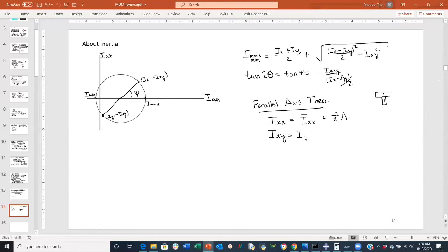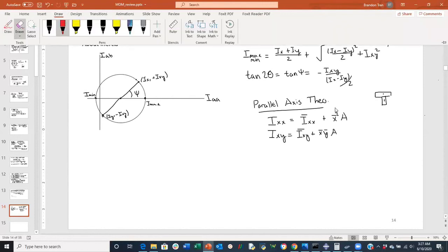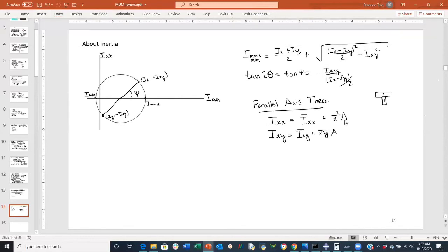And then this is the only other one I want to mention. That specific portion is the cross-sectional moment of inertia, plus the distance from the centroid of the whole component to the centroid of that part in the x and in the y, times the area. So there is that. Okay, just make this look a little cleaner. So there is that.